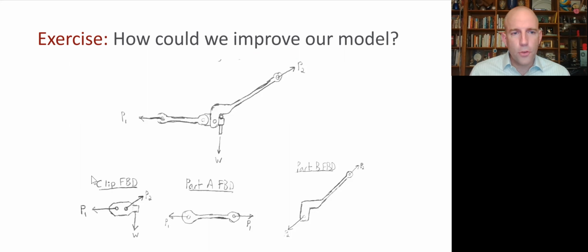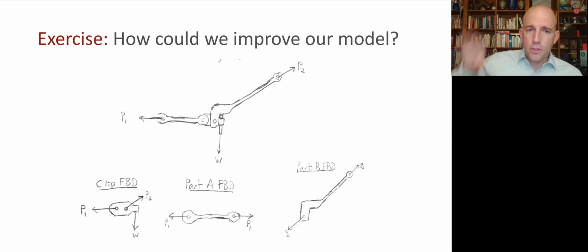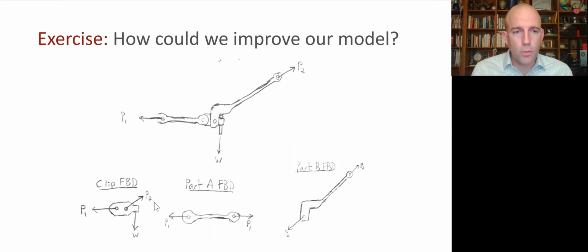So if we look at the free body diagram of the clip, we'll see that if we take moment balance about this second peg, both of these forces pass through that peg. So their lever arm about it is 0. But the weight, that force that's on that rope, well, that has a finite lever arm. It doesn't go through that peg. And so that will cause that peg, the whole clip to spin, right? You can't achieve static equilibrium with this free body diagram.